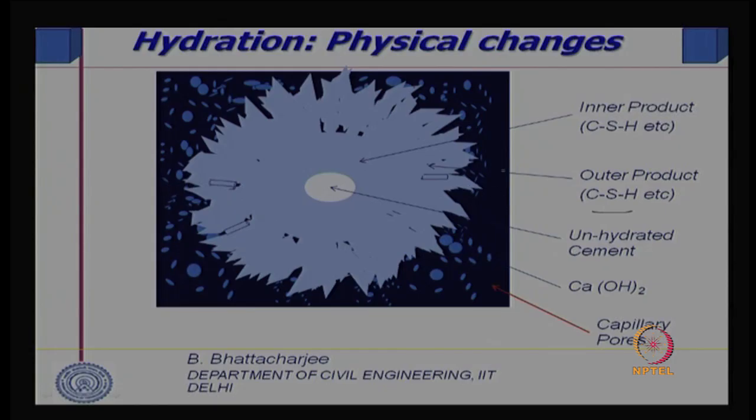But remember, there will be a large quantity of pores remaining at the initial stage, unless you have very little water, less space to be filled by the solid products of hydration, and the reaction continues over a long period of time. We will look into this in some more detail later on.